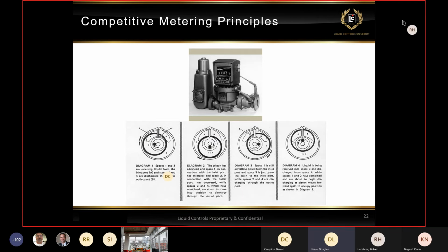Here again is the meter principle when you're looking down into the metering chamber. So this is stage one, where the product comes into an inlet. It forces the piston around, and it goes to the outlet, which you'll see in the next couple of slides. Those dark areas now are where there's going to be wear. Through the years, they've tried to improve the wear, but also these are all brass components, and the meter was at one time all cast iron body.